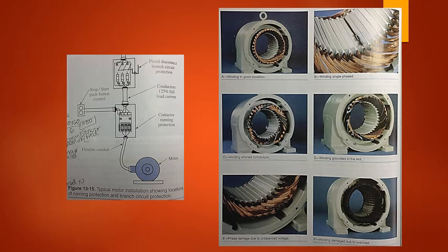In a motor, there is very little clearance between the stator and the rotor. As the bearings wear down, the rotor will begin dragging on the stator. Usually this causes a loud roar or high, shrill, winding sound as well as excessive vibration. The worn bearings cause excessive load on the motor and cause it to go into an overload condition.